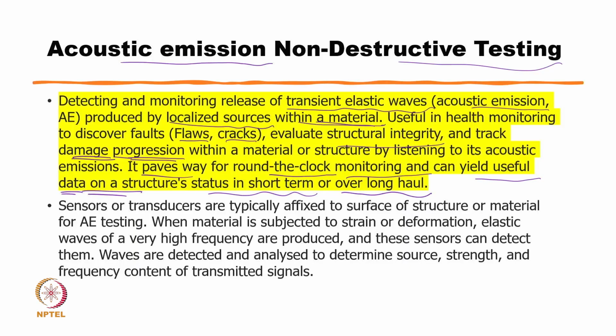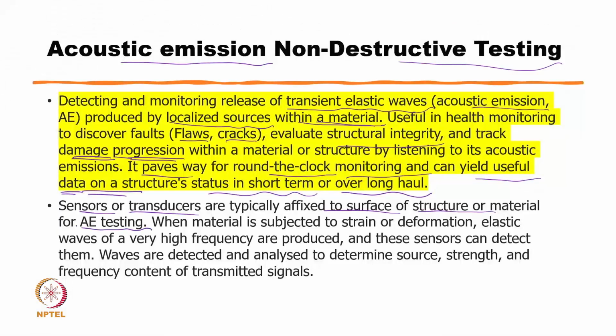Now, another point in this situation is that the sensor or transducer available to us needs to be attached to the surface, because the sensor plays an important role. If it is attached to the surface or to the material, then it will capture the acoustic emission, and then we need to do analysis. It can be time analysis, it can be frequency analysis, and we should have a database to interpret those results.